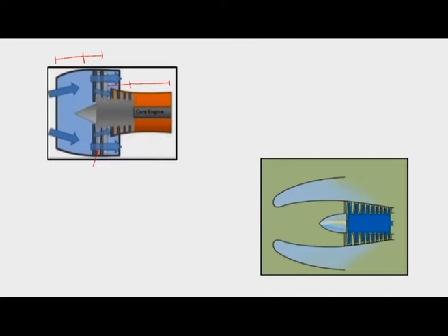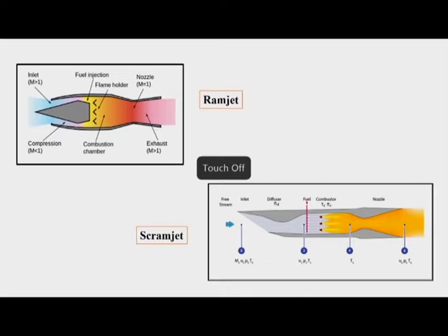In general, in an engine we would have different shapes of intake, as we have seen in the earlier picture. This is one of the pictures of the intake, where the air gets compressed during its path in the duct, which is the intake. So, practically, pressure rise and decrement of velocity are the objectives of the intake. Based upon the requirement, we have different types of intakes.